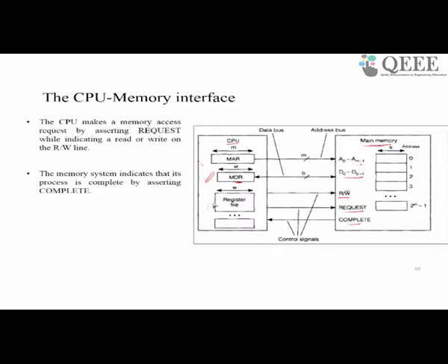The processor may also have some register files. Let us assume that the width of the memory address port is M bits. So the MAR is an M-bit register, and the address port of the processor is M bits wide, numbered from 0 to M minus 1. Let us say the width of the data is B; then B lines is the width of the data bus, and the data bits are numbered from 0 to B minus 1.